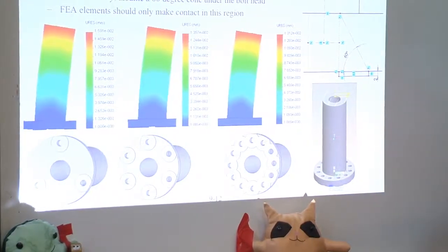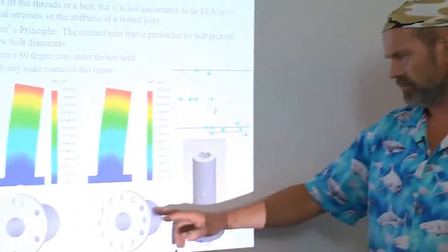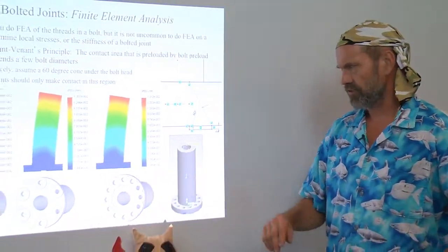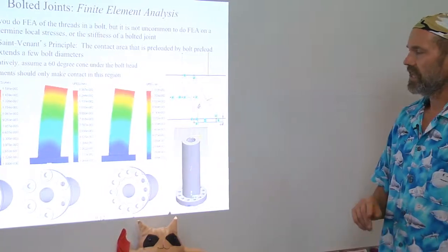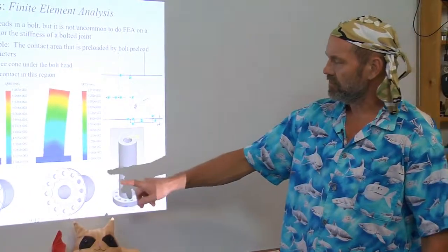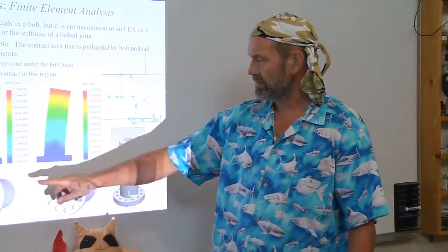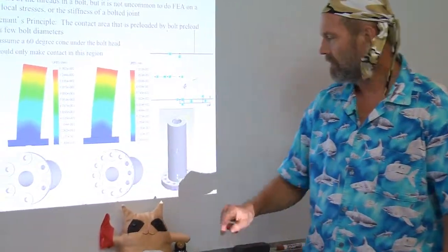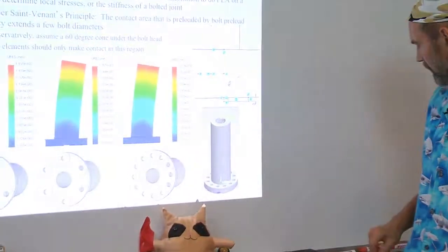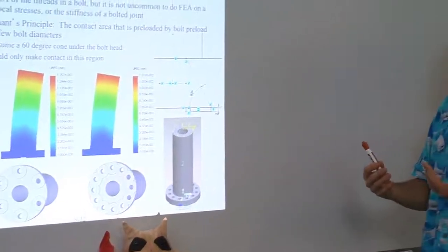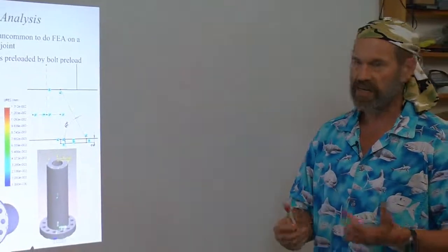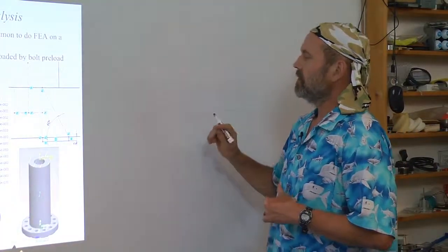The management person in you would say, we have to minimize cost. You can use 12 bolts. That's very expensive. Why don't you just use 6 bigger bolts? Now, looking at the base here, why do we have these overlapping circles? What these overlapping circles are based on, from doing a solid model of the machine and then doing a finite element analysis, is the following.